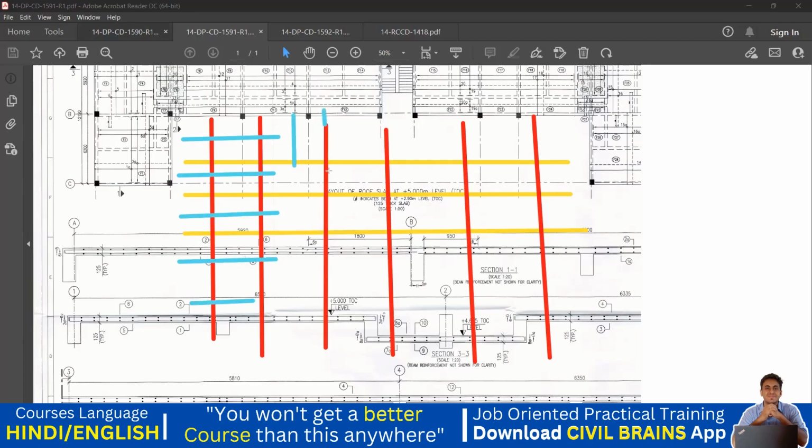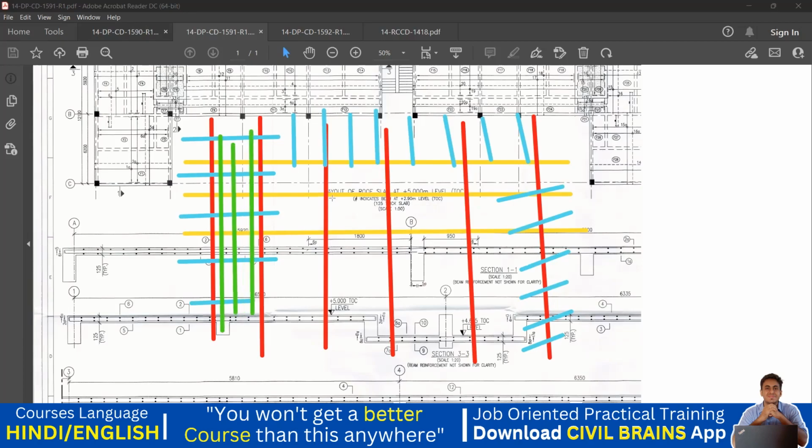Similarly on this side. Most of the time it will be a two-way slab only, but it depends. This is a cut reinforcement, actually the top extra bar we have given, and of course you have to give a distribution bar to this. Below this your distribution bar will come. This distribution bar will be for the top reinforcement. For reinforcement you are going to get bottom straight, bottom vertical, top straight, top vertical, right? Same thing will come on this side also.